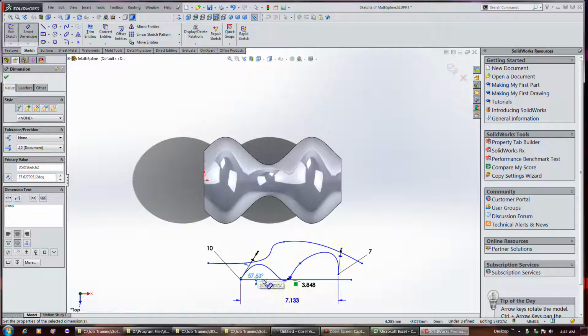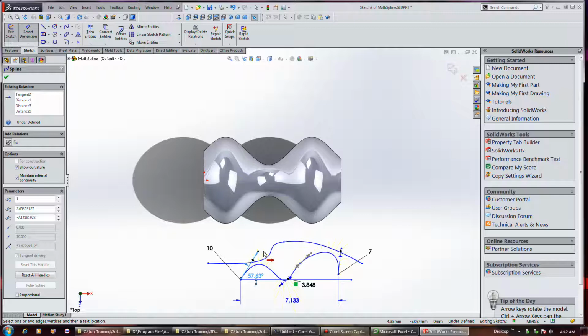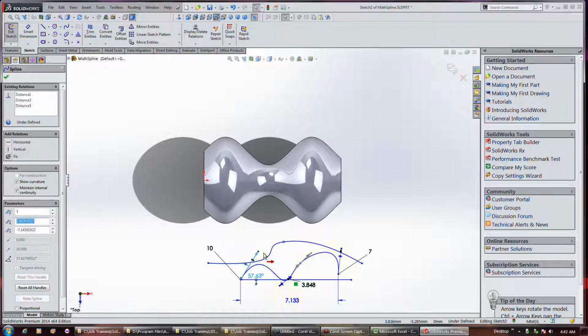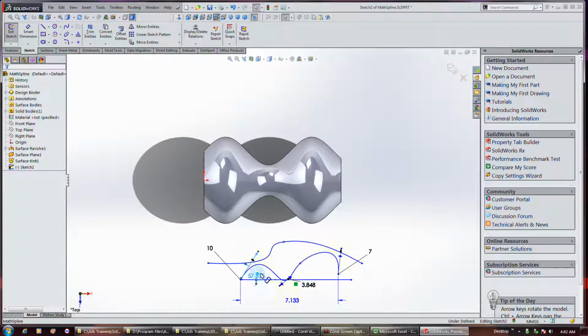If you want to add an angle dimension, you need another reference. Obviously you can't reference it to itself, but you can add an angular constraint, so that way this dimension is pretty much fixed, because it's angular. We define the length and we define the angle here in between these two.